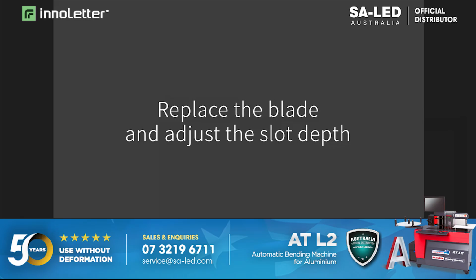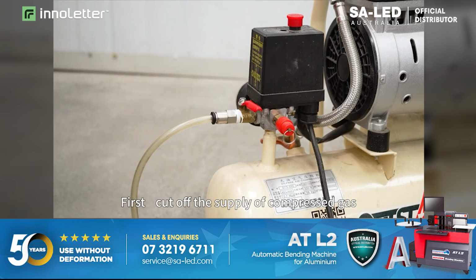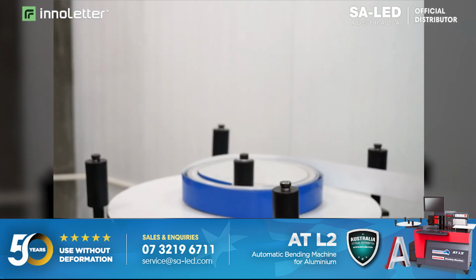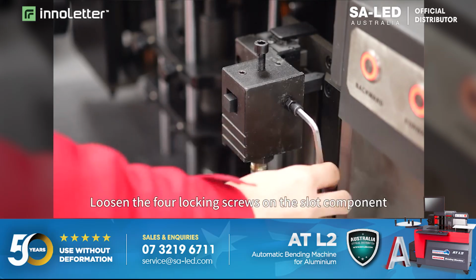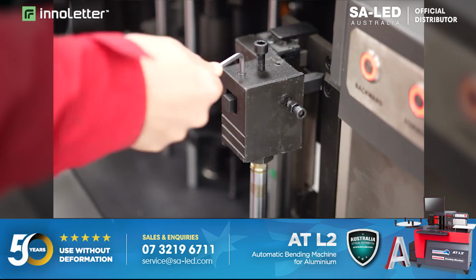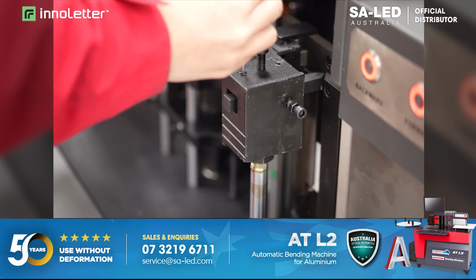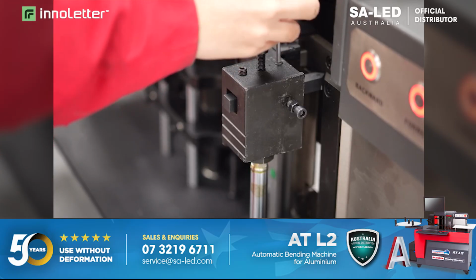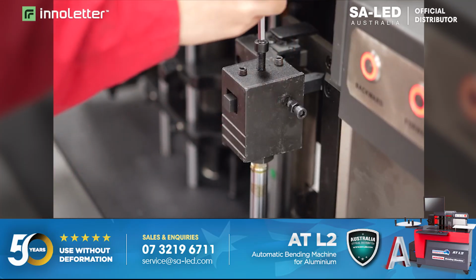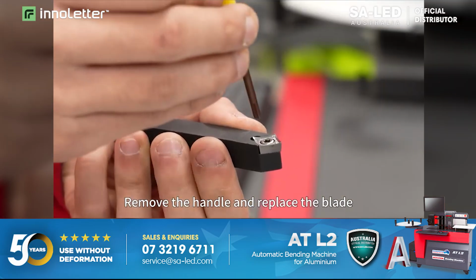Replace the blade and adjust the slot depth. Cut off the supply of compressed gas. Release the remaining compressed gas. Loosen the 4 locking screws on the slot component. Remove the handle and replace the blade.